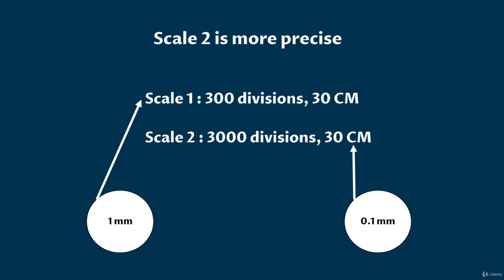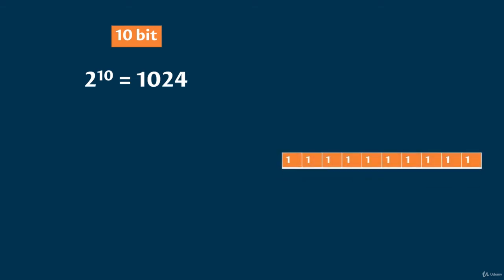If I put this example in context of Arduino Uno, then in ADC, the resolution decides the precision. How? The resolution tells you the minimum voltage an ADC can measure. In Arduino Uno, the controller Atmega 328P has a 10-bit ADC. So maximum divisions can be 2 to the power 10, that is 1024. That means the result of ADC conversion process is always a 10-bit value.